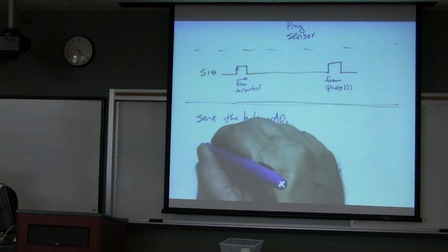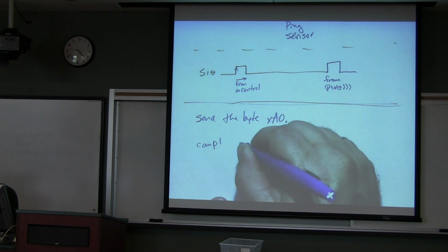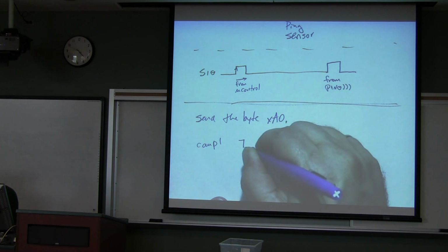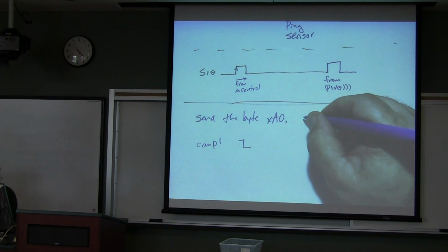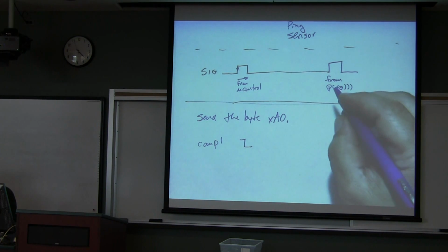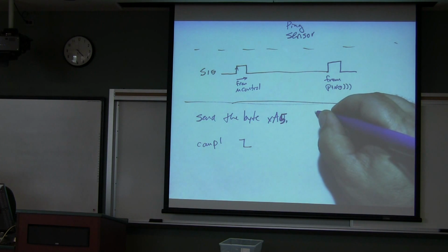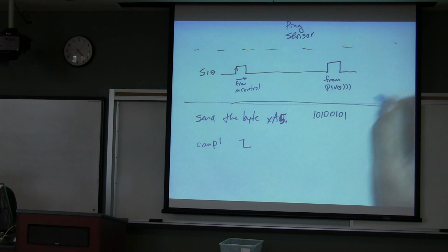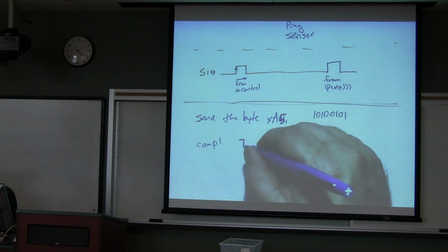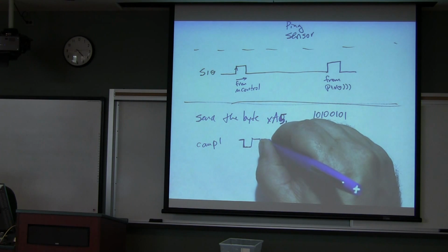So from computer 1, I'm going to send the start bit. Now, A0 is... actually, you know what, I'll send A5. That looks easier. So that's the pattern 1 0 1 0 0 1 0 1. Wasn't that convenient? So then it's going to send logical 0 for the start bit. Then the next bit is going to be logical 1.